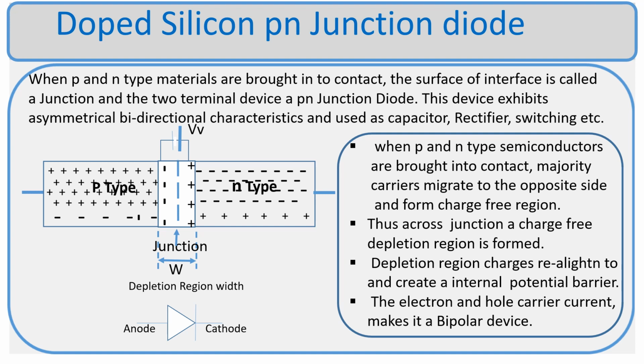The reverse breakdown characteristic of a PN junction is controlled by silicon doping level and thereby create avalanche and Zener diodes. These devices are operated in reverse breakdown region and are used as voltage regulator diodes. A reverse biased diode, operating in non-breakdown region, acts as a semiconductor capacitor and is known as a varactor diode. Thus, the diodes operated in different regions are used for different applications.